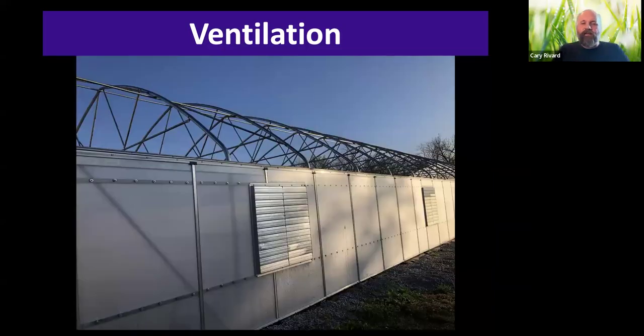We can also put our louvers on the sidewalls of the greenhouse, and we might talk about that a little bit later. Keep in mind that if you're ventilating a greenhouse from side to side as opposed to end to end, you're going to have a lot of hot air that builds up here, right? And we'll talk about that in some of our later webinars when we talk about heating and cooling inside the greenhouse. But it's something to consider for sure.